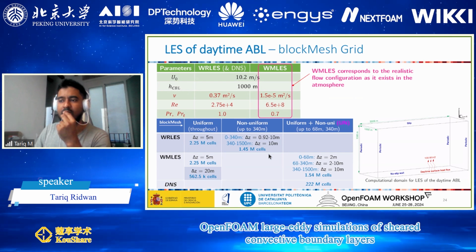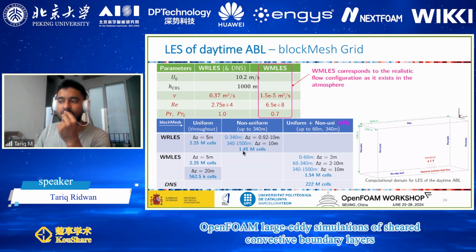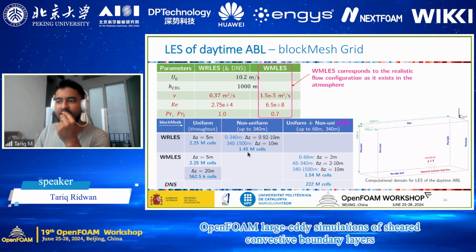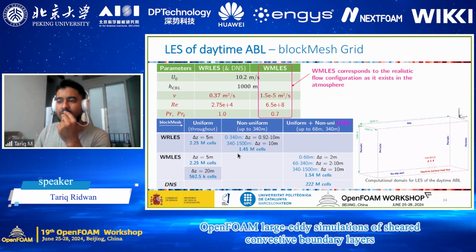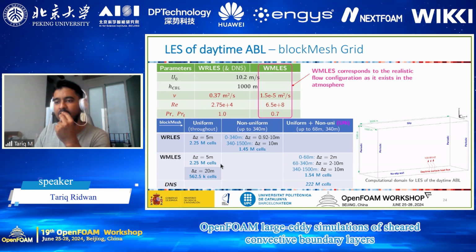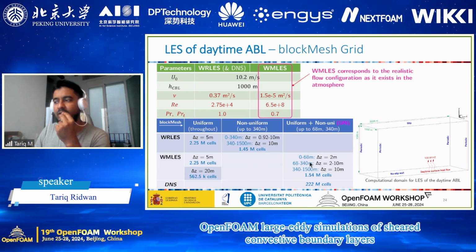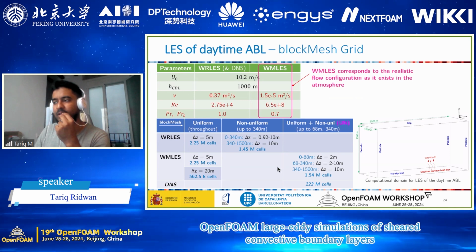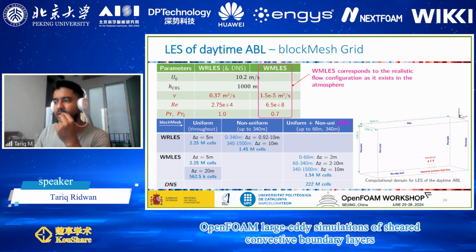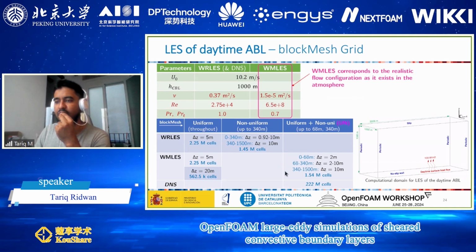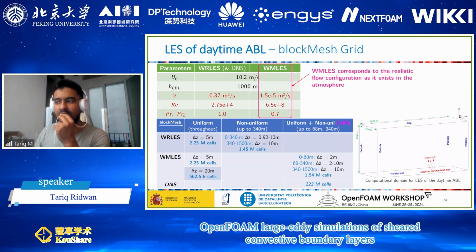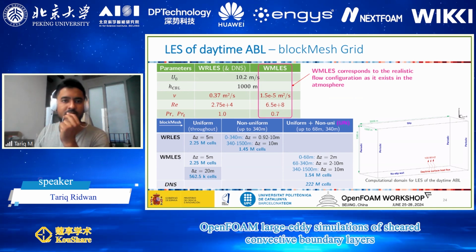And also the subgrid scale model Smagorinsky is giving better results overall. So using that knowledge, we applied Smagorinsky only in the wall model LES. We are still working on grid convergence. We'll try a little higher resolution and move to other wall functions. But in general, the wall model LES did a pretty good job, we would say.